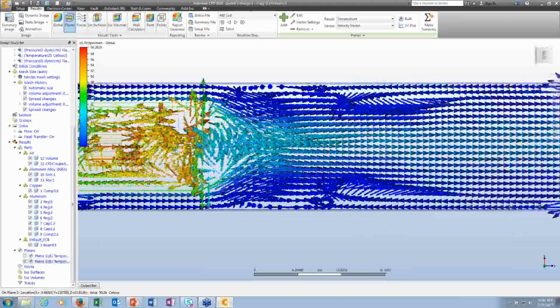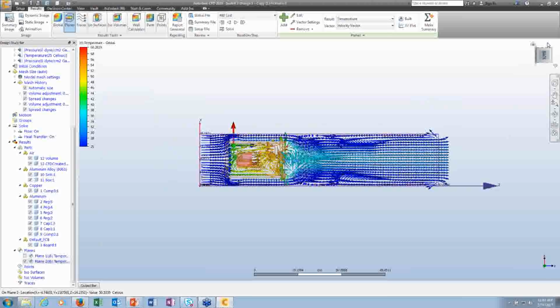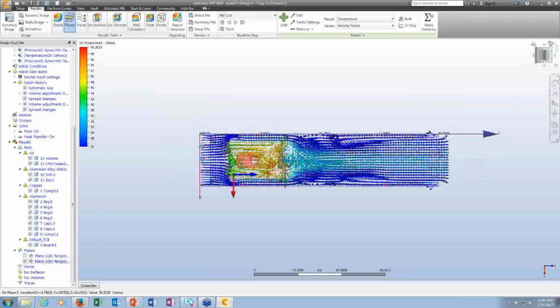The other thing I wanted to touch on is basically picking between turbulence models. It's fine to use K epsilon. Some people in this application use mixing length, which is going to produce a less turbulent flow. It could definitely be more accurate for your application. Just remember, if you choose to use mixing length, you're going to have less turbulent flow around the electronics, less convection heat transfer, and probably some higher chip temperatures.